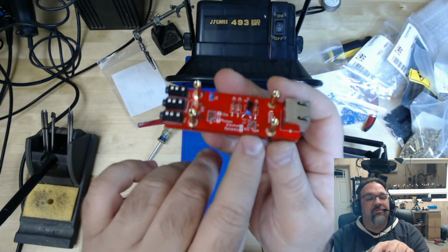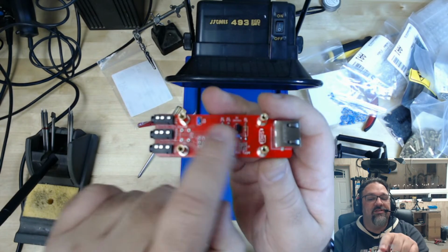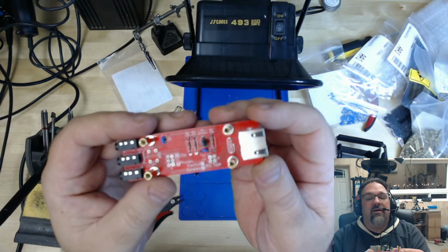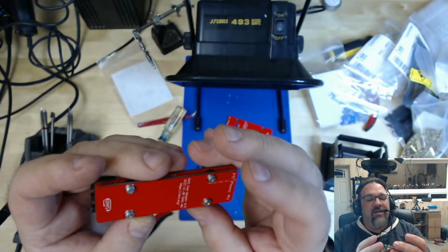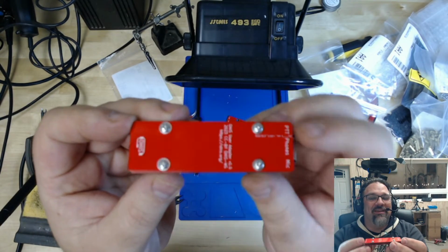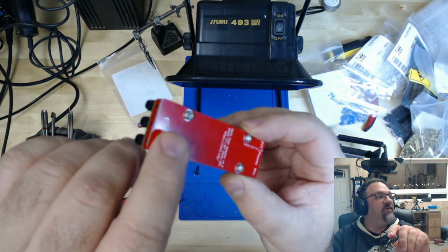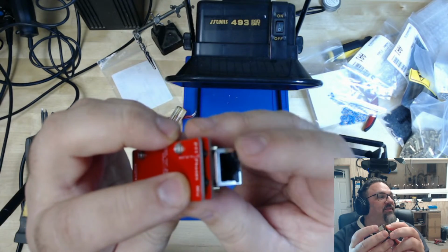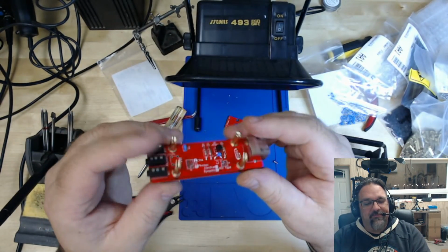And then this one over here enables or disables the mic preamp, which are these 5 components there, 3 resistors, a capacitor, and a transistor. And then that makes the OHIS. Sweet! Okay, so I was originally thinking that this board isn't really oriented in any way, but it kind of is, because I have the OHIS by the 3.5s, and then the labels for the 3.5 by the OHIS. All right, so I screwed that up. But that's just cosmetic.